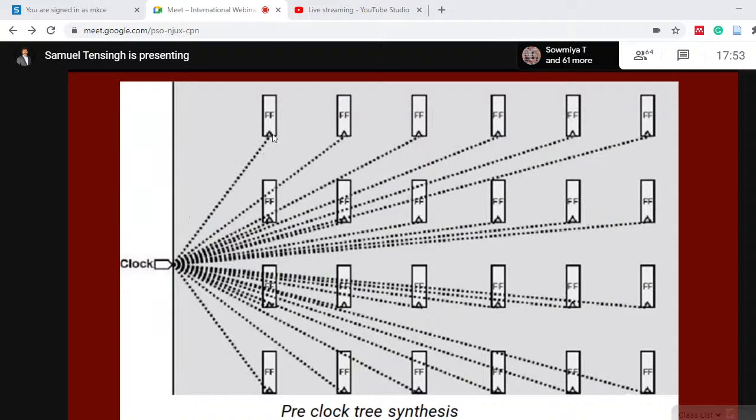When you do a timing analysis, the distance between these two is very small, whereas the distance between this and the last one is very long. When you compare these two, this is a very short route and this is a long route. In this case, it is very hard for you to balance the clocks and close timing.